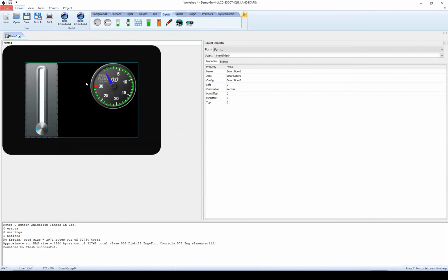The last setting when it comes down to the slider is just to do some fine tuning on the touch surface. I need to put some offset into the extremes so that when you're touching this, it's not only a small part of this particular object, but it covers the entire button here. That's done by setting these offset values here in the properties under Object Inspector. In this case, the values are 38 pixels and 38 pixels at the top and the bottom. And now, basically, this particular object is completed.